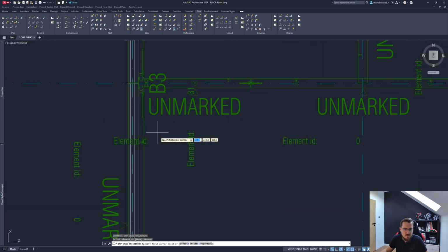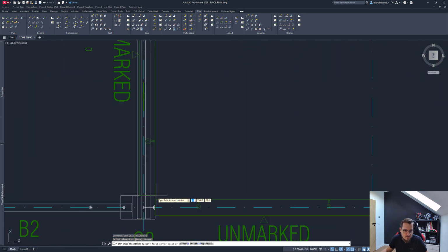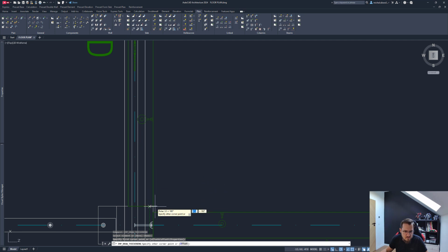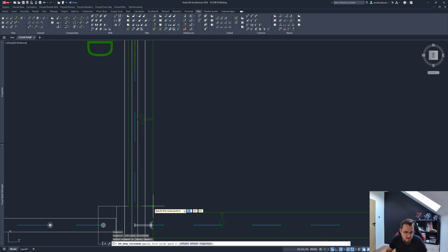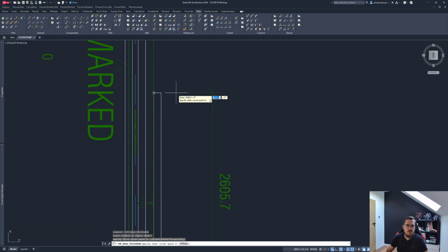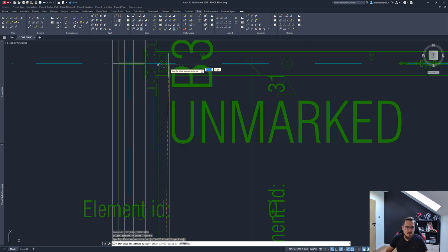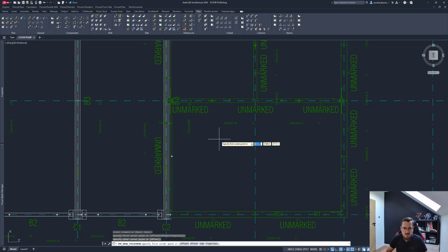So I selected the element, and what I'll do now is I'll start from this point, and as you can see, it grabbed my panel thickening in a wrong place. So let's do that again. Wrong snap, basically. So let's snap to the edge here. Perfect. That's perfect. And I'll go and I'll reach this point. Right. And that should be good. I'm going to space and accept that, update all lifts, and let's see in the 3D model how that looks like.